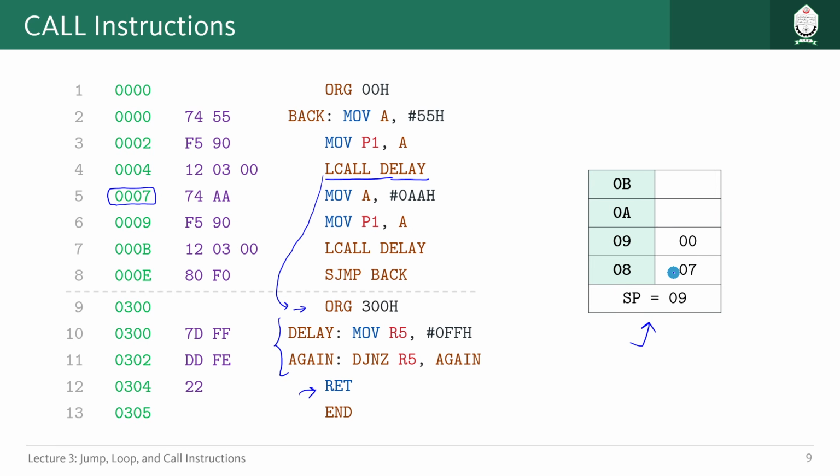Because of that, it will understand it has to start executing from this line, because the program counter always guides the processor to execute line by line which instructions we have to execute, right? As we change the value of the program counter, instead of executing anything here, it will return here and start executing from here. In this way, the stack pointer and stack help with that.